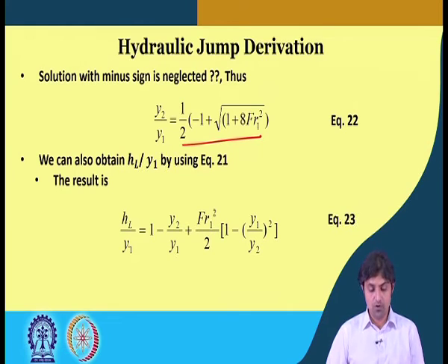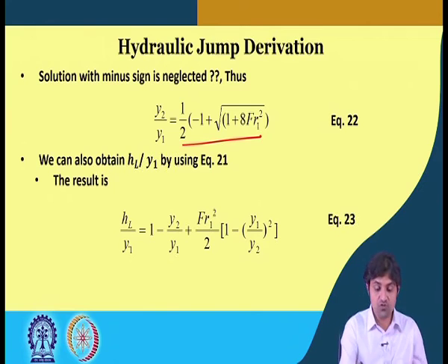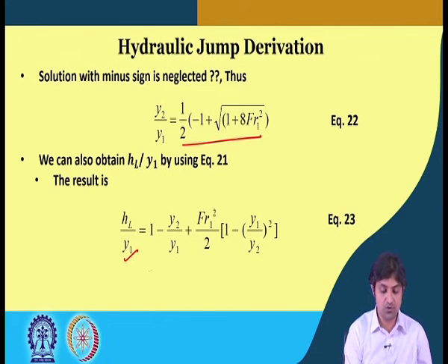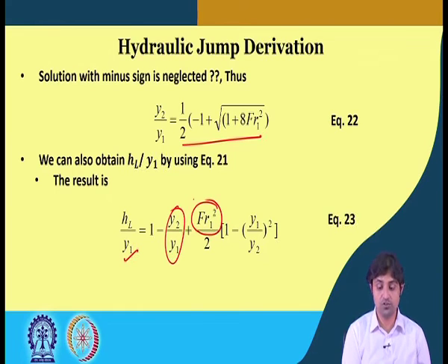We would want to find out the situation after the hydraulic jump has occurred. So, in most of the cases y2 and v2 and those things are unknown. So, y1 is known, using this formula we can also find y2 or y2 by y1. So, this is known, Froude number at 1. So, if we know everything at section 1, Froude number at 1 is also known.